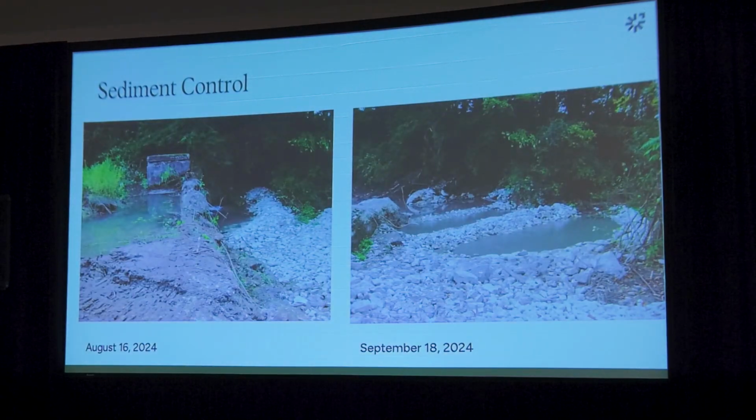Here's an example of sediment control on a dam that was completed this year, Wainwright, down in Salisbury, Vermont. You can see the contractor installed a series of riprap filter berms just downstream of the dam, which worked really great because, as water would pour over the dam and be carrying some of the sediment from the upstream work area, it would then filter through the riprap, and they could periodically dig out these pools and prevent the sediment from just moving downstream.